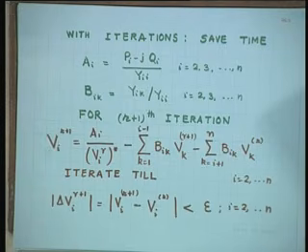If these are rough planning calculations, then even 10 to the power minus 2 is okay, minus 1 is okay, and so on. It depends on the desired accuracy, that means the purpose for which you are conducting load flow. As I have repeatedly said, load flow is required in practically all power system studies, be it stability, economic operation, security, or fault studies. These things will be more clear when you solve a numerical.